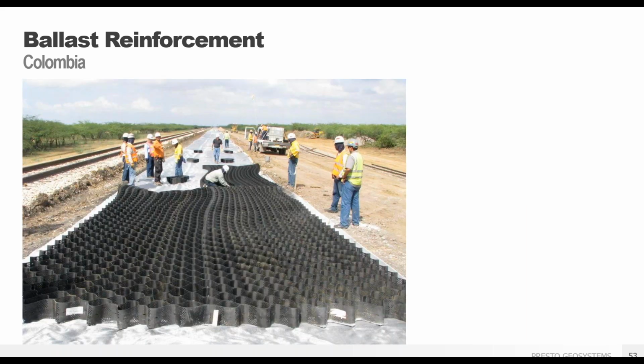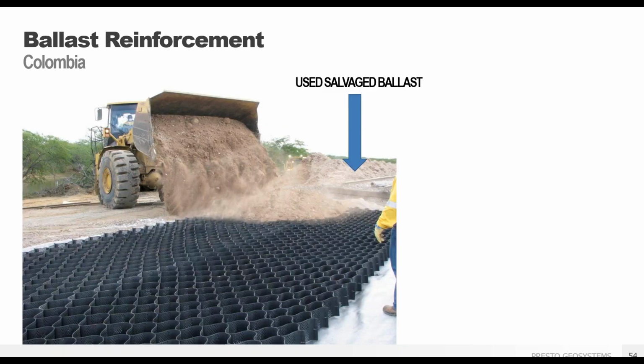So they approached us. We worked with the engineer and the geotech. Once we provided the design with an enhanced woven geotextile, you can see that getting installed, and also 2 panels of GeoWeb. Each panel here, for a typical track for us, is a lot of times 17 feet wide. You can see connecting the 2 panels together, extending over the GeoWeb and the geotextile.